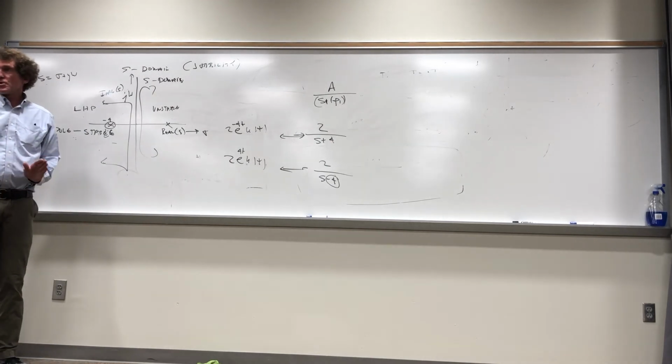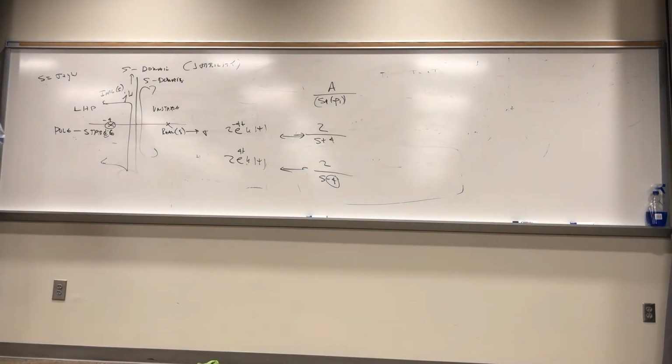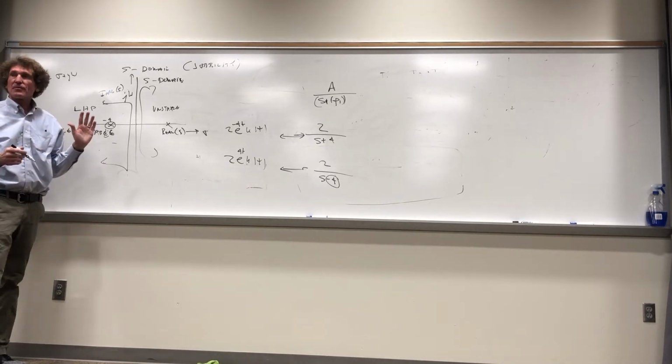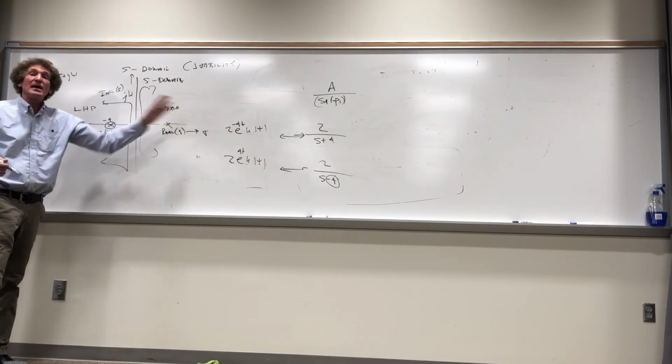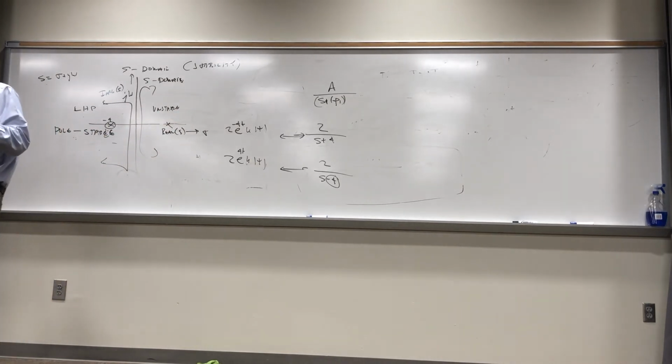Follow me? So this is very important for stability analysis, and it comes in a little bit when we do this. When you get a system, you can do pole zero constellations. You can get that real quick with MATLAB. If you see any pole in the right half plane, after you do feedback and stuff with your system, you have a major problem. Your system isn't going to work well. And if it's designed to blow up, you've done a great job.